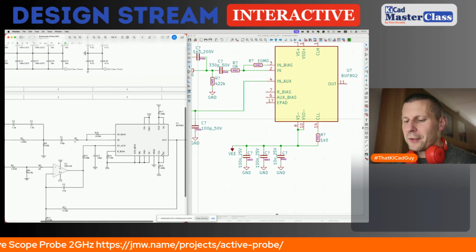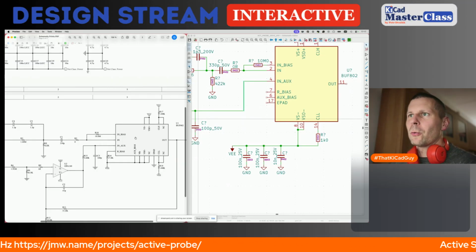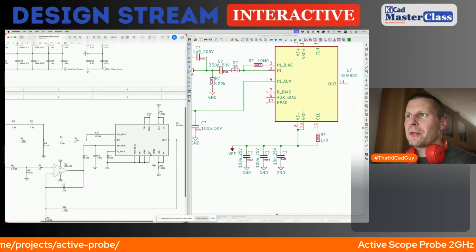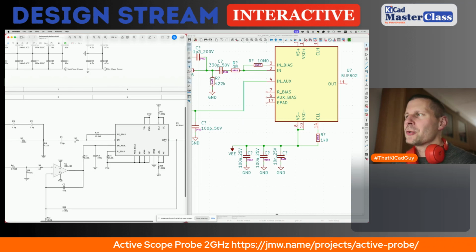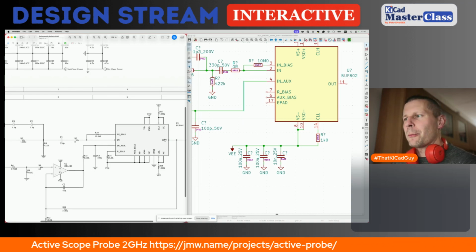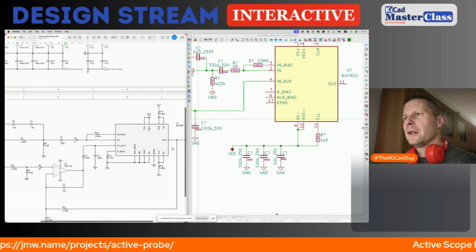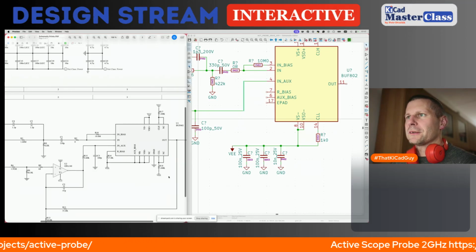There are no pin numbers, so you don't know which NC pin is mentioned here. There are three of them. I encourage you, always use pin numbers for at least ICs, always.